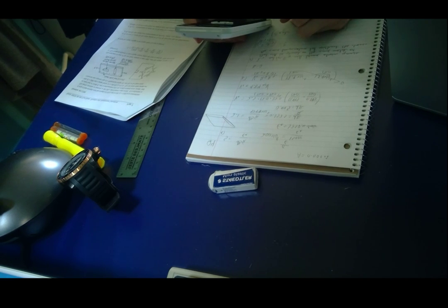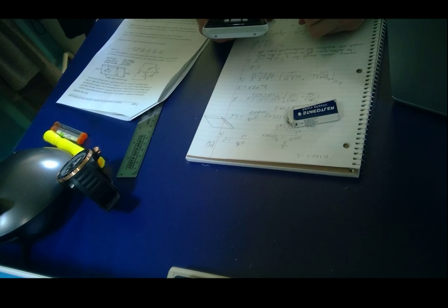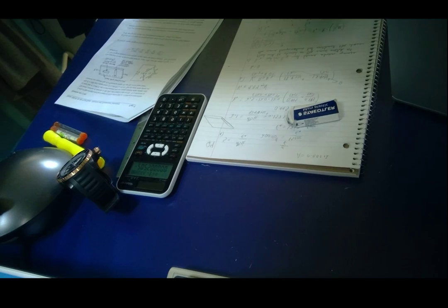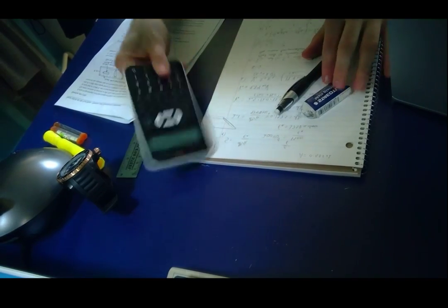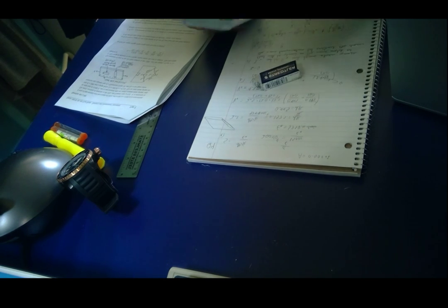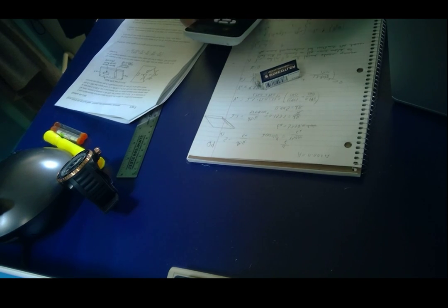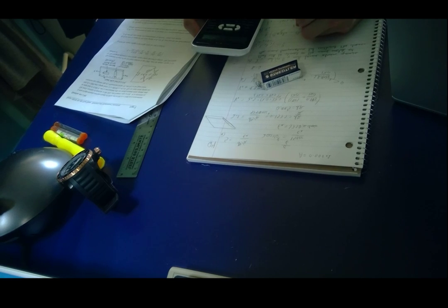So it's minus 2025. It's minus 202500. No, that's stress. What am I saying? That's stress. Whoops. No, it's just E minus 6, because that's microstrain, and then you do times minus 0.27 times 1e6. So we get minus 1012.5 microstrain in the transverse direction.